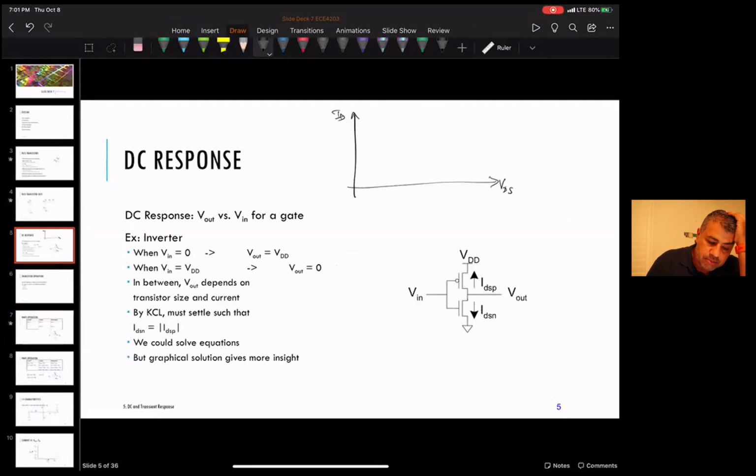One was I think called the Shockley model, the first level model, where we had these VGS high, mid. And then we had the way it really works, which had these upgoing curves, and the current wasn't going to be as high because of electric field effects.